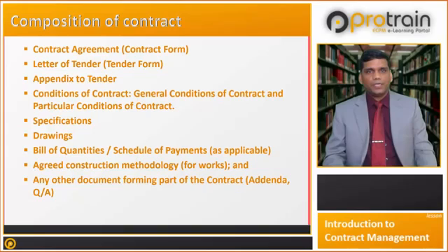contract. It assumes a remeasurement form of contract, although that does not preclude the inclusion of a number of lump sum items in the BOQ, provided their scope is adequately defined under the contract. In EPC nature of works, a schedule of payment having a breakdown of the lump sum cost defining the components of the works, filled in by the contractor at the tender stage, is included.